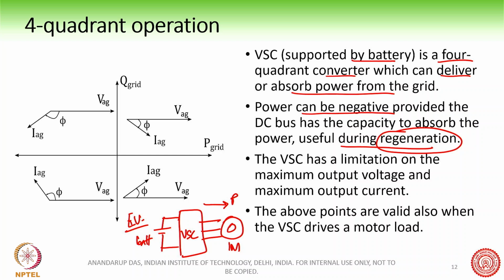But when the EV is going down the slope, for example, then we have a chance to do regenerative braking, which means that when it is going down the slope, we can feed the gravitational kinetic energy back into the battery so as to save some energy. Otherwise, the car will actually accelerate very fast, right? So we need to brake it. The way we brake it is that we convert the kinetic energy of the car into electrical energy, which is fed back to the battery.